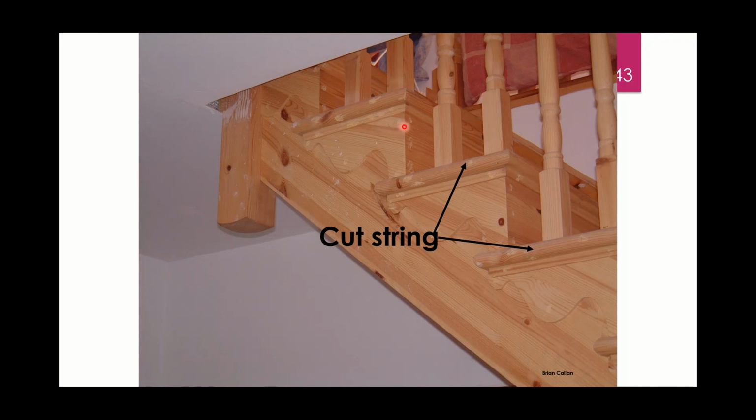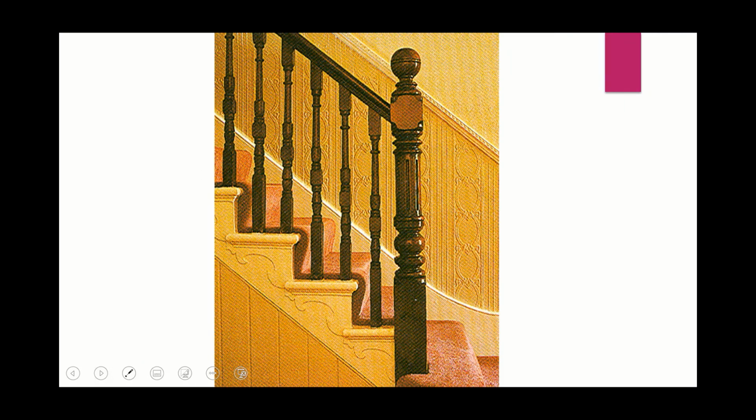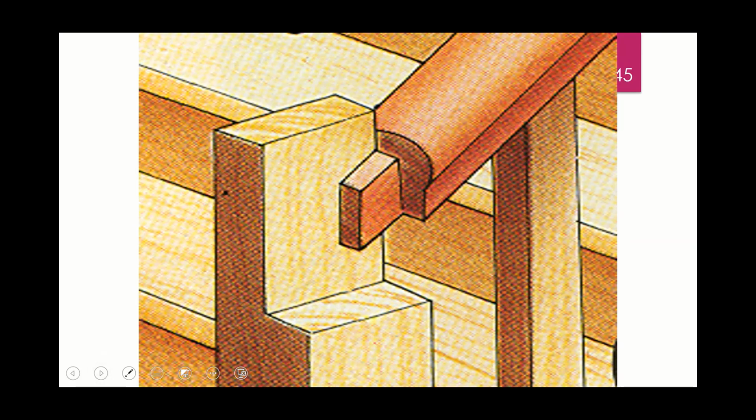So if you see a set of stairs like that where the string has been cut out and the balusters go straight down, that's known as a cut string stairs or an open string stairs. Okay. You can see there that's an open string stairs. What we've looked at so far is if you can imagine this string going straight up along there and that's all covered. It's closed essentially, that's a closed string stairs. That's just showing the handrail, which is also mortise and tenon into the newel post.